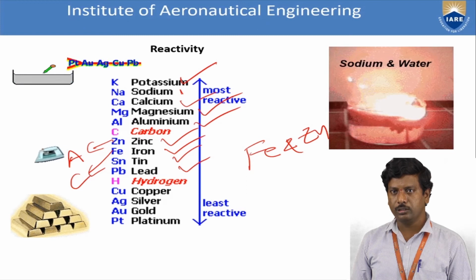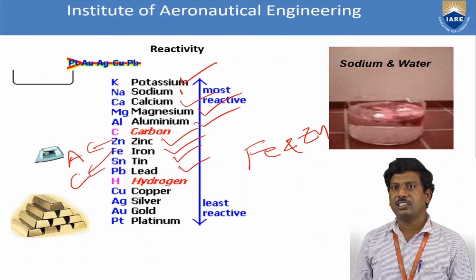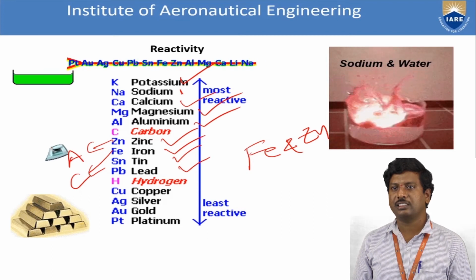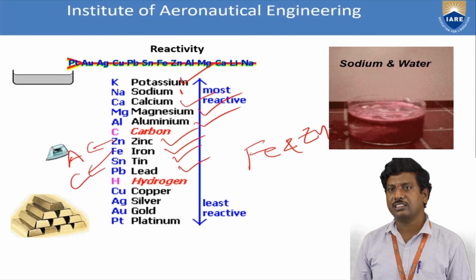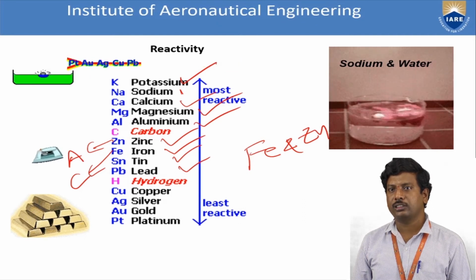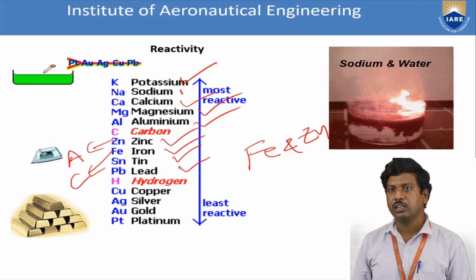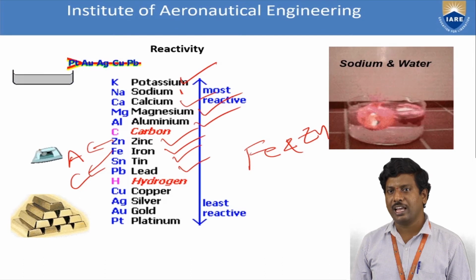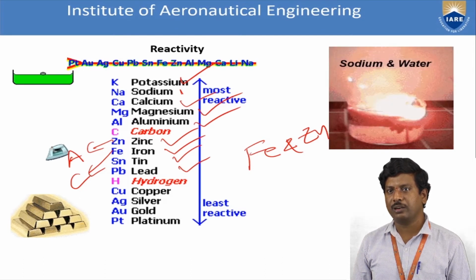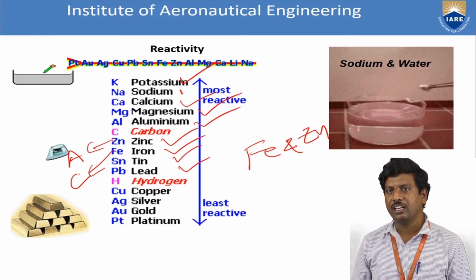Because of this, zinc always acts as an anode and sacrifices its life compared to the iron. So iron acts as a cathode and is the safe-side element. If iron is the most essential element, the iron can be coated with zinc, and the zinc undergoes rapid corrosion.